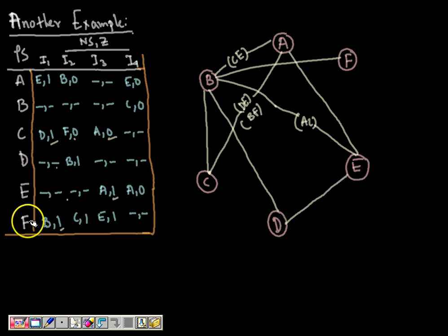Between DF, it's not specified, 1 1, it's not specified 1, same. So D and F should also have an arc between them, but it should be an interrupted arc because the output and state transition is different. It depends on B and C. So between D and F, it should be BC.